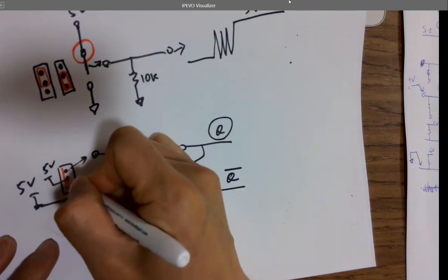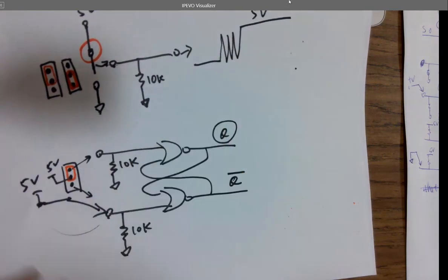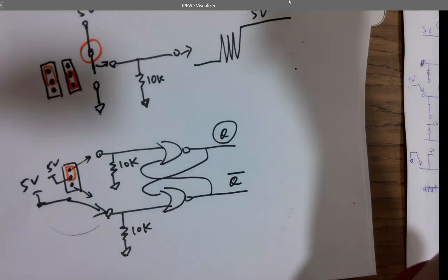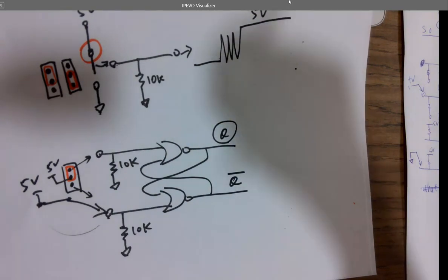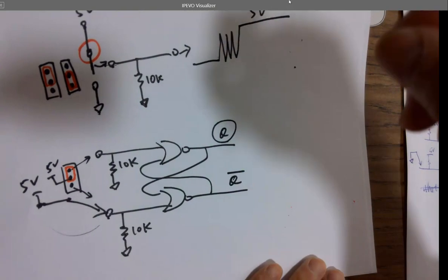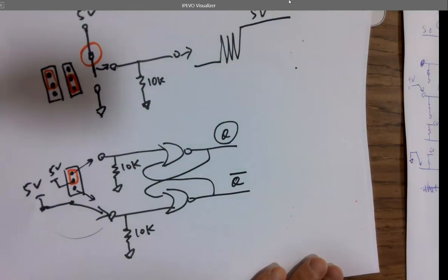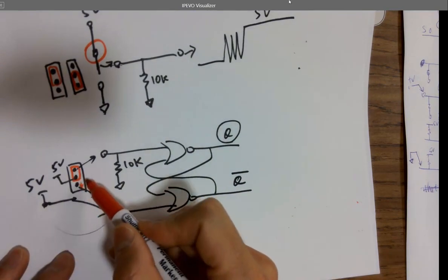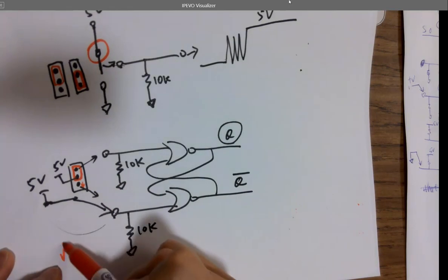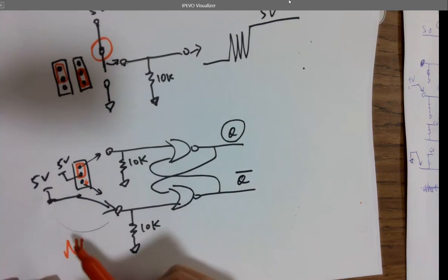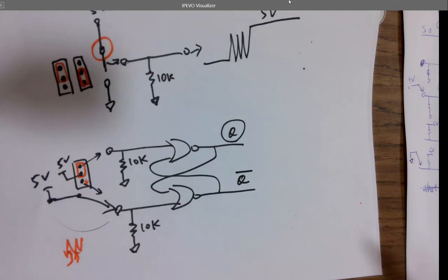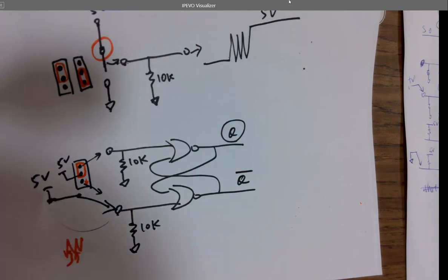You switch it to the top or bottom, right? When it's in the middle, it's 0, 0, so it's just looking at memory. When you move it, your hand is slow, but you think you can switch it really fast. Compared to the clock frequency of the computer, it's really slow. Whenever you switch it from here to the bottom, it vibrates a lot, so there will be a lot of noise being generated. Your computer is reading really fast, running all the loops really fast, so it is able to read every single data point in the noise, giving you a really noisy output.